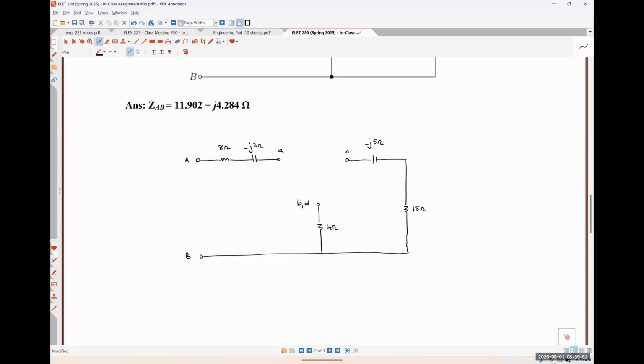So when I do problems like this, where I'm replacing a portion of a network with its equivalent circuit, I like to imagine in my head that I'm literally removing that network, transforming it, and then connecting it back to the exact same set of terminals. So that's the way that I make sure that I always reconnect things properly, okay?